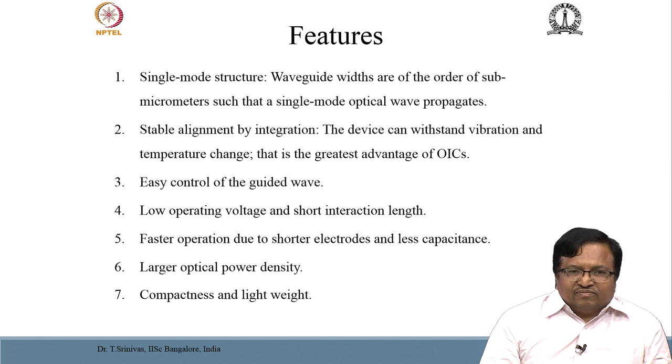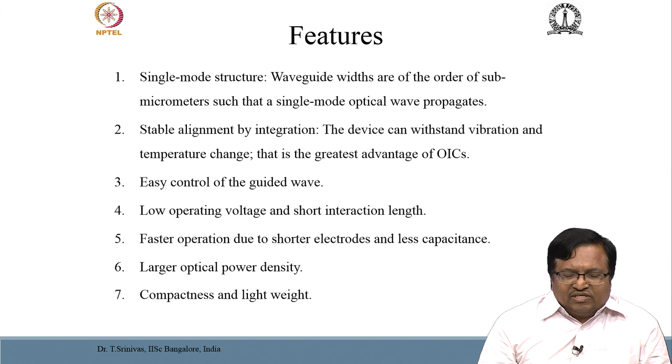The power density of light propagating in these waveguides is very large. So, you can expect many nonlinear effects which can be used effectively in photonic integrated circuits. Of course, like in VLSI circuits, these are very small, so they are very compact and lightweight, they consume less power, and batch production can be used to fabricate devices and so on. These are the generic advantages of going for miniaturization and batch production in photonic integrated circuits.